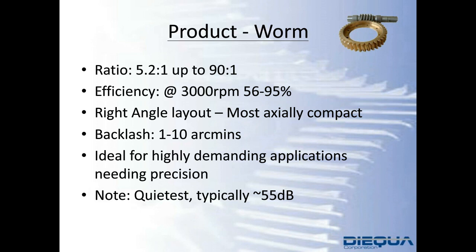And it is a gray scale, very much at 5:1, 10:1, 15:1, you'll be able to backdrive the reducer. So say you have your linear actuator, your power is cut off, but you're trying to move the table back to its original position. It'd be rather straightforward to apply force on the output table and then backdrive the reducer, backdrive the motor, so it allows you to home in with a power outage.